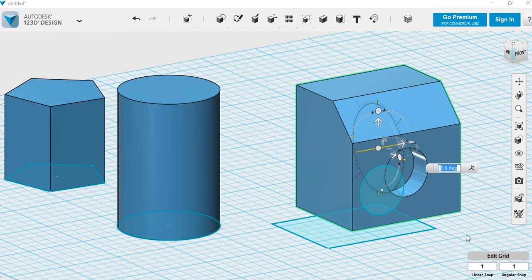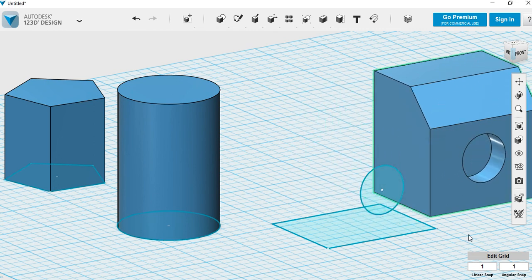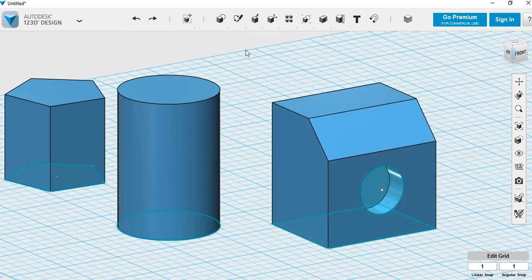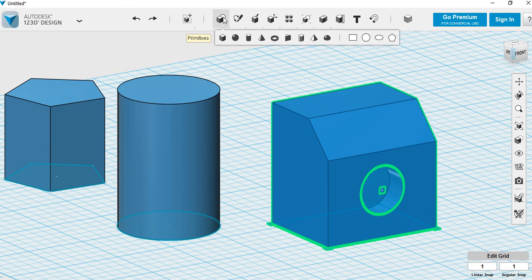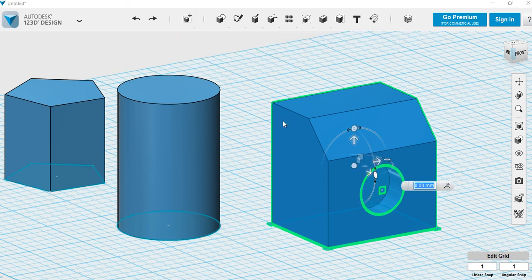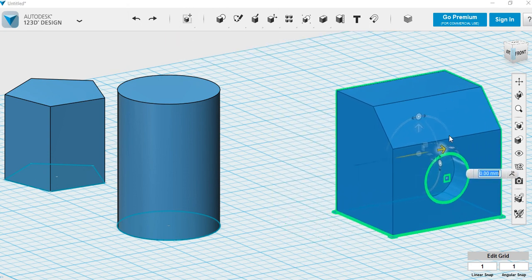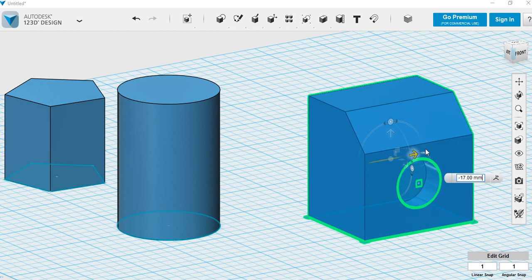When you move the objects, please be aware that you do move them away from their original sketch. So if I was to move this block aside here, the original sketches would stay in place. To move them with the sketches, I'd have to click and drag around it, and then click on the move tool, and then when I move the block, the sketches go with it.